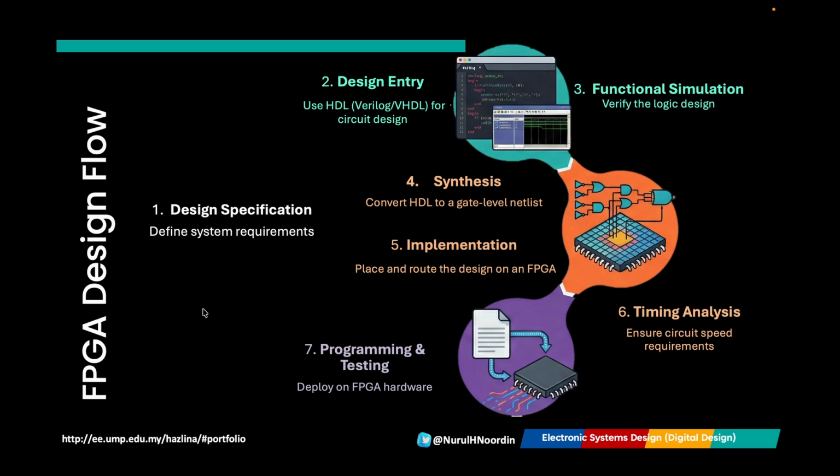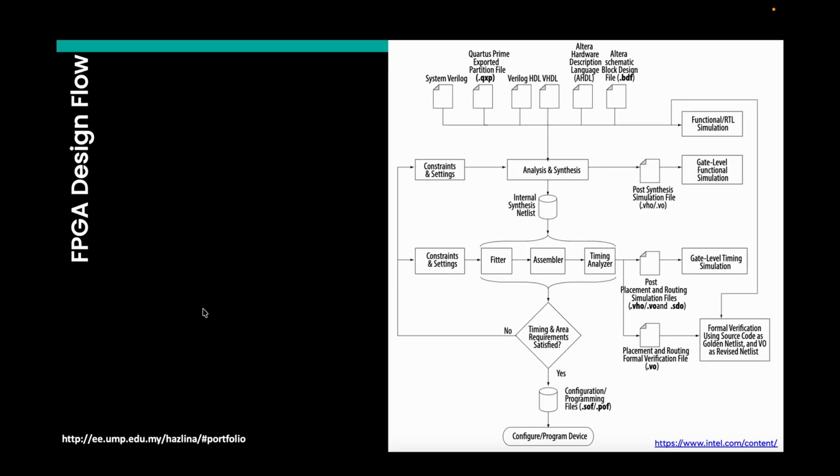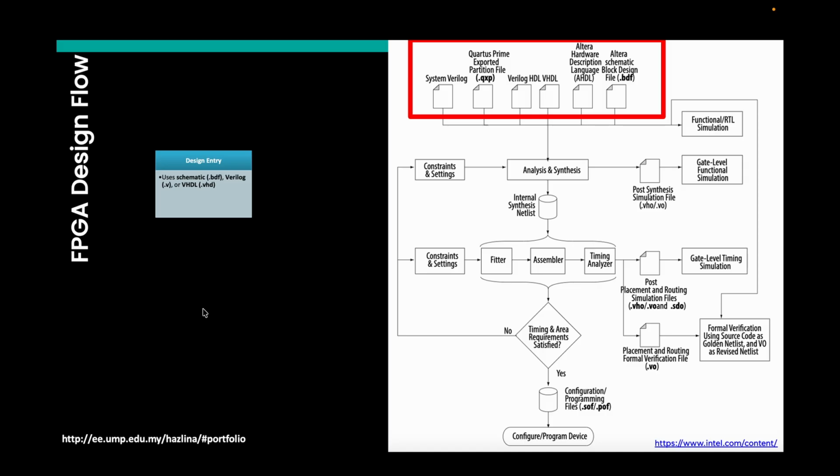So the IC design process consists of several key stages, from defining system specifications to final testing and validation. Let's explore each stage of this Altera FPGA design flow in detail. First, we define the system specification. These include requirements like power consumption, clock speed, and overall functionality. For example, in a Pico satellite like the Lilex 5 onboard computer (OBC), the system must process sensor data efficiently and communicate via LoRa wireless transmission. These steps ensure we understand the constraints and the objective before we begin designing.